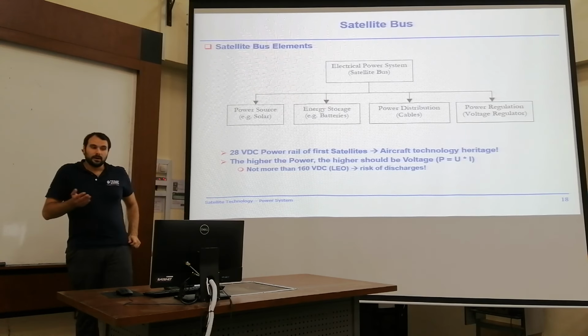That means you need to find a way to charge your batteries. I doubt that you want to bring an artificial sun into your clean room. You can do that for testing purposes, huge lamps, they're really warm and bright. But usually, you're better off just having an auxiliary power input, feeding in here over the diode, and then if you close all the switches, from here you can directly charge the batteries.